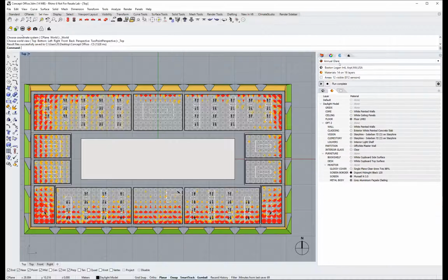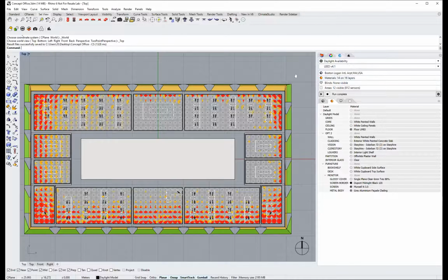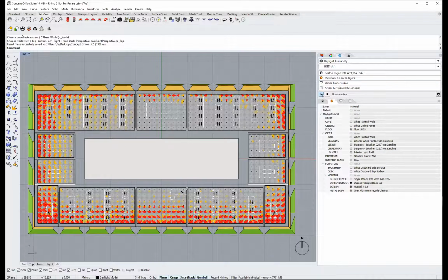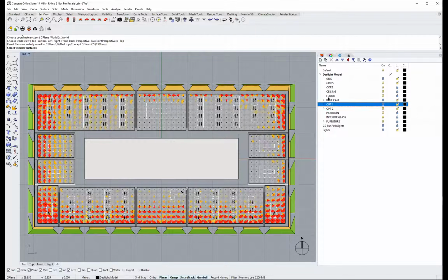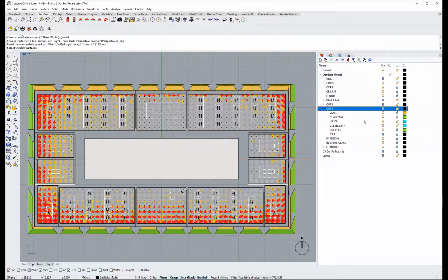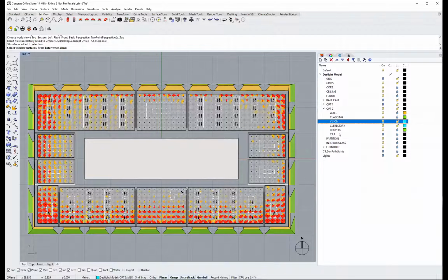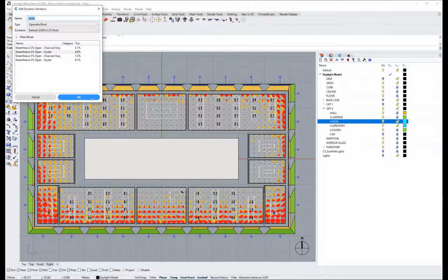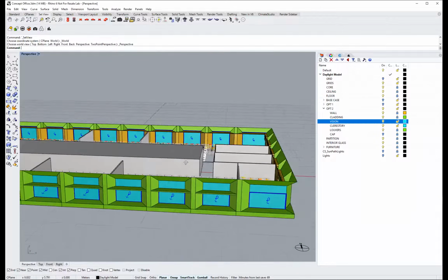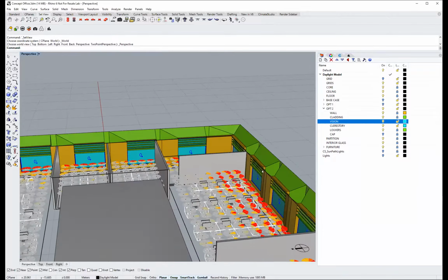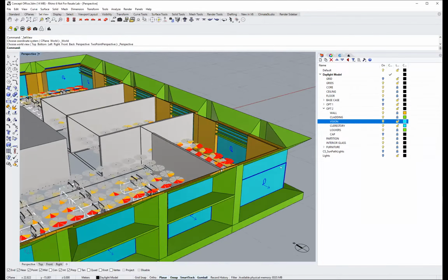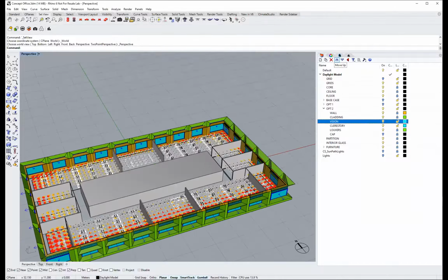And I'll switch back my question to daylight availability. And of course I need to specify the blinds again. Now here I'm going to say that I don't really need blinds in that clerestory portion because it's always blocking direct. So I'll just pick within option 2 my vision glass. Okay, and so what you're seeing here is now we just have operable blinds on the lower part of the glazing, and the upper part with the louvers always has the fixed shading. Okay, so let's start that.